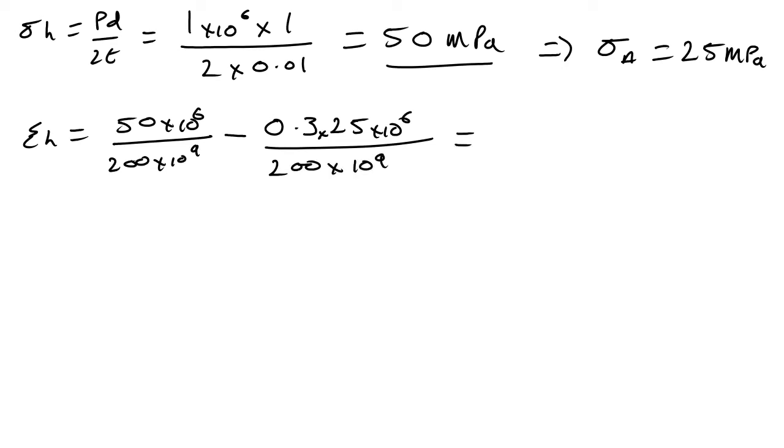And if you do that calculation, I get 212.5 microstrain, so that's times 10 to the minus 6. We can do the same thing for our axial strain.